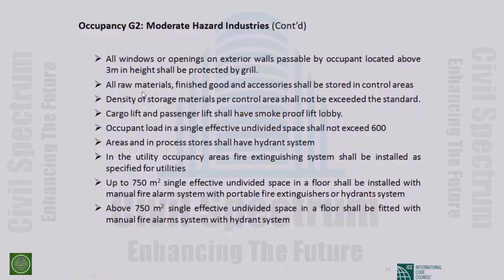All the raw materials, finished goods, and accessories shall be stored in control areas. The control area means an area which is at least 1 hour fire rated. So all raw materials, finished goods, and accessories shall be stored in control areas.